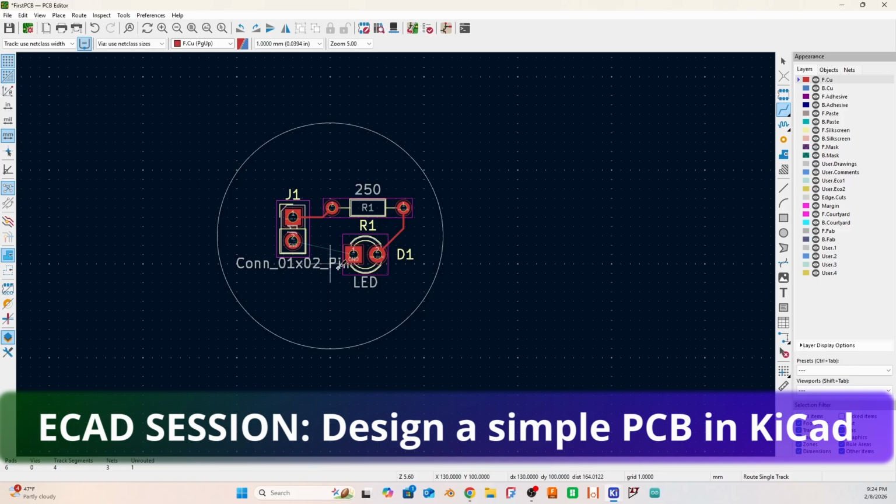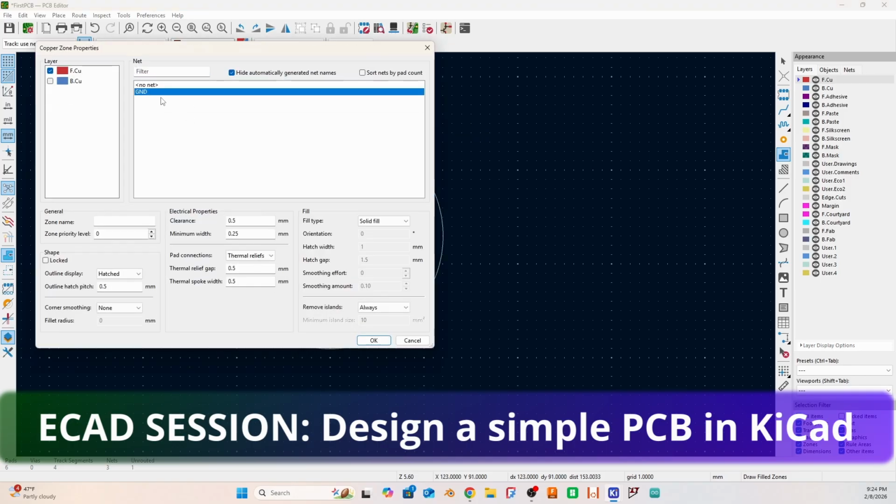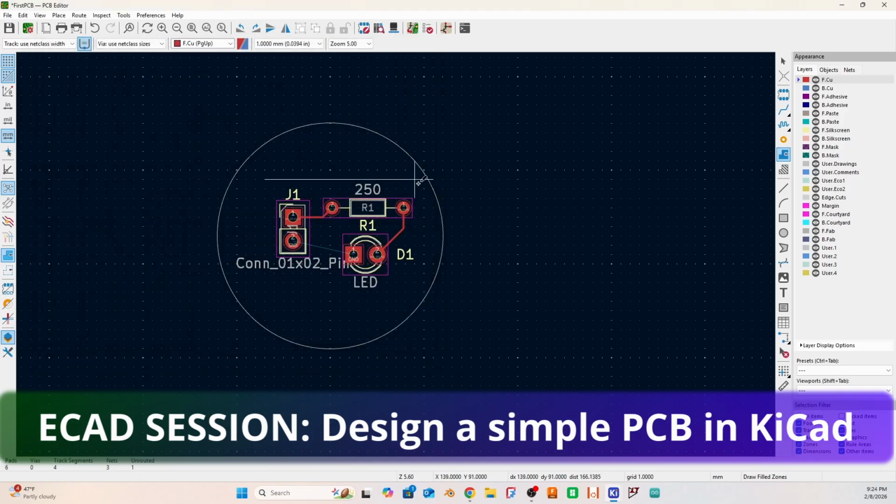For the ground we don't need wires, so we're just going to put in the copper inside. Very simple. We come here, select this one, and then fill in the copper. Okay, select the first edge, and then select ground. So we're going to connect all the ground with copper. Okay, second edge, and we just created a zone here.